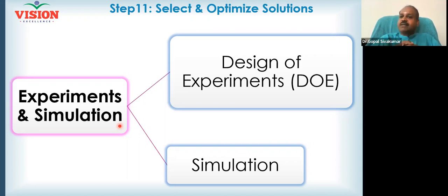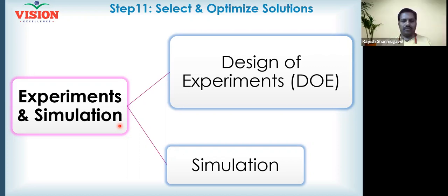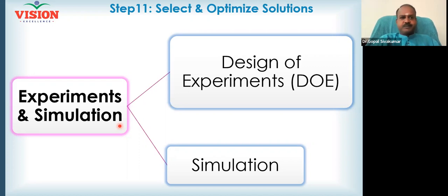The airflow will have turbulence, required to mix the fuel and air so that fuel can burn better in the presence of air. So the second factor is turbulence. The third factor is time. When I give more time, more fuel will get burned. So I just have to make settings.